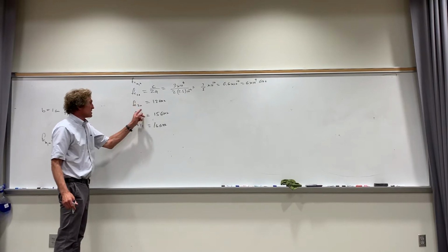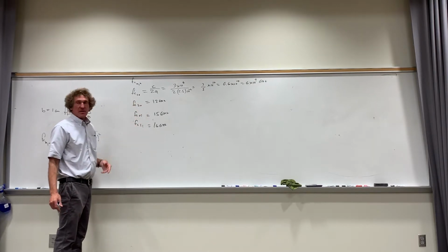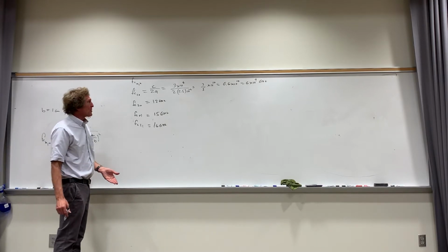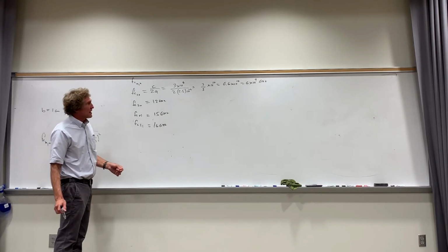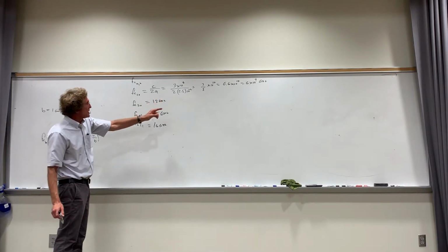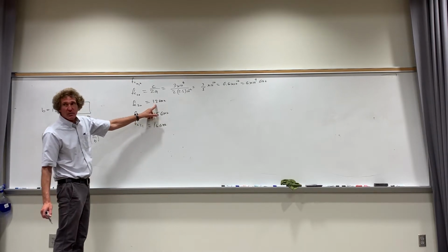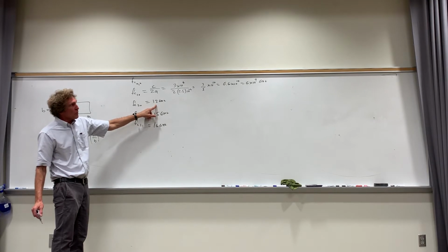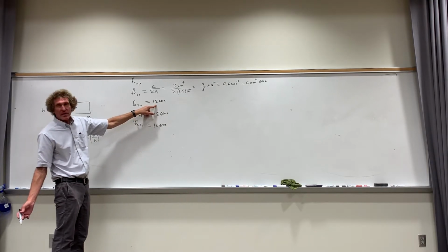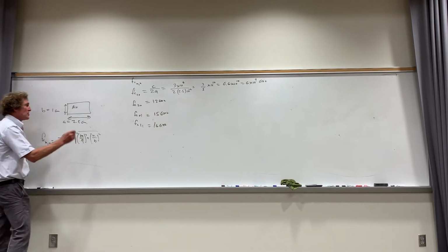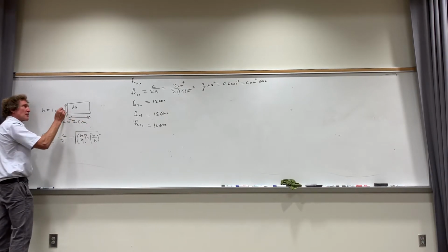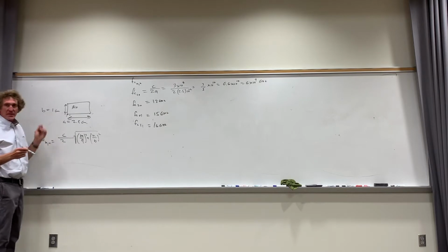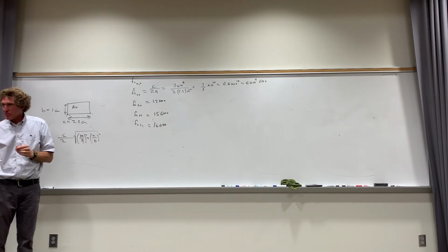Now what I'm showing you is this. As these numbers increase, 1-0, 2-0, 0-1, 1-1, you can see the frequency gets higher and higher. When you would operate this, typically, the cutoff is 6 gigahertz, and the next mode starts in at 12. So you would want to work between 6 and 12 gigahertz. Usually the ratio of this side to this side is about 2 to 1 or 2.5 to 1. That's the reason I chose those dimensions.